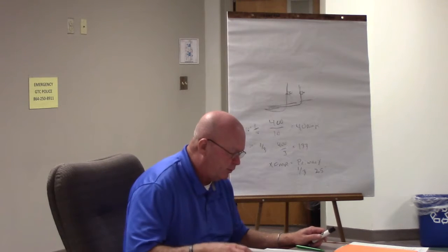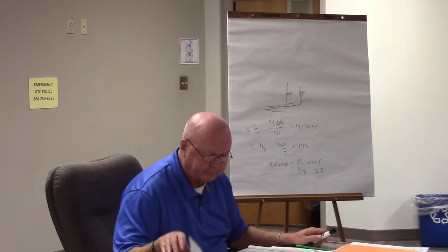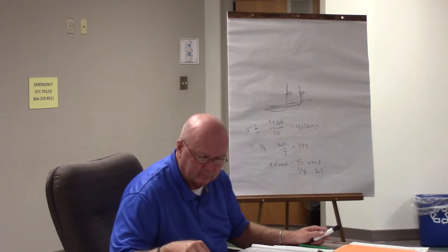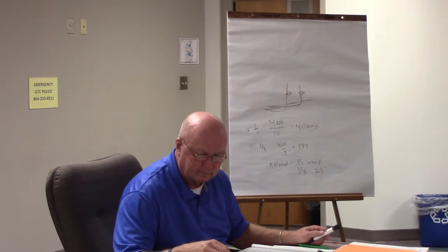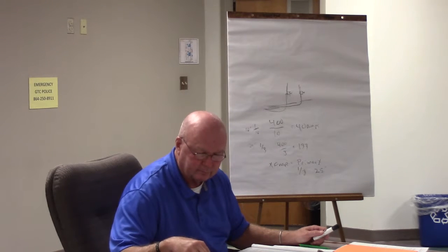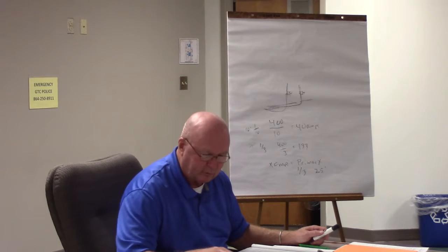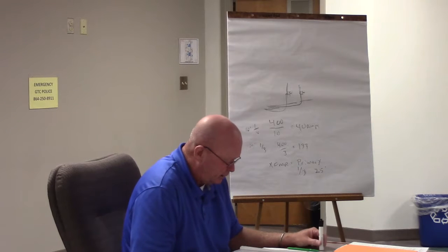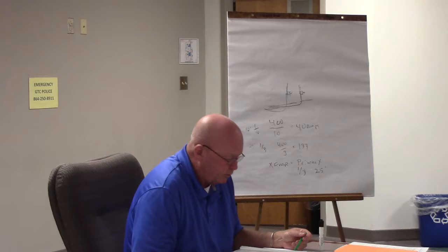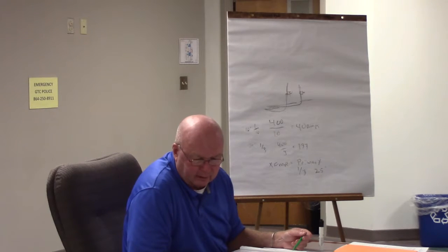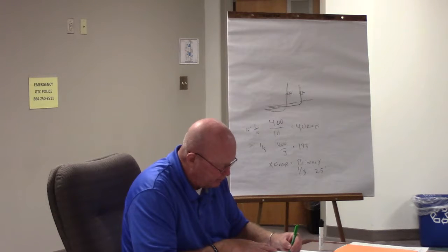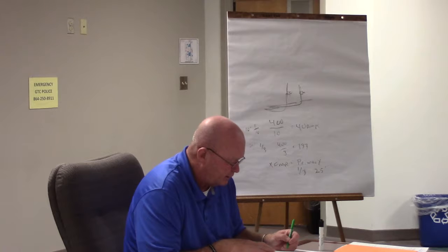Transformer secondary conductors, 240.21C. Transformer secondary conductor, back where we were at earlier. Code there is talking about transformer secondary conductors. We look here, code 240.21C3, so we look at C3, which says industrial. C3 will permit secondary conductors from a transformer in lengths up to 25 foot in industrial, and this is the key when you're reading your book here, in industrial installations only when the following conditions are met. Now, what is industrial?